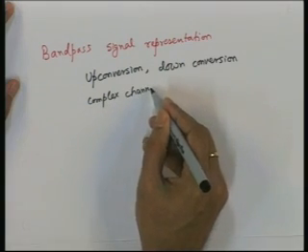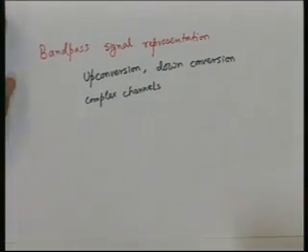and complex systems, though in real life the physical channel is a real channel and the transmitter and receiver both are dealing with real signals. But then why complex channels come into the picture, we discussed in detail, and we saw that if we have a band pass channel, that is a channel for which we are going to use only a pass band, a particular bandwidth, then we can design the signal in the baseband after shifting that spectrum to near 0, and then do something called up conversion, which means shifting that spectrum to the pass band where we want to transmit it, and then transmitting it. At the receiver we can again bring it back to the 0 frequency, that is called down conversion, and then process the signal in the baseband.